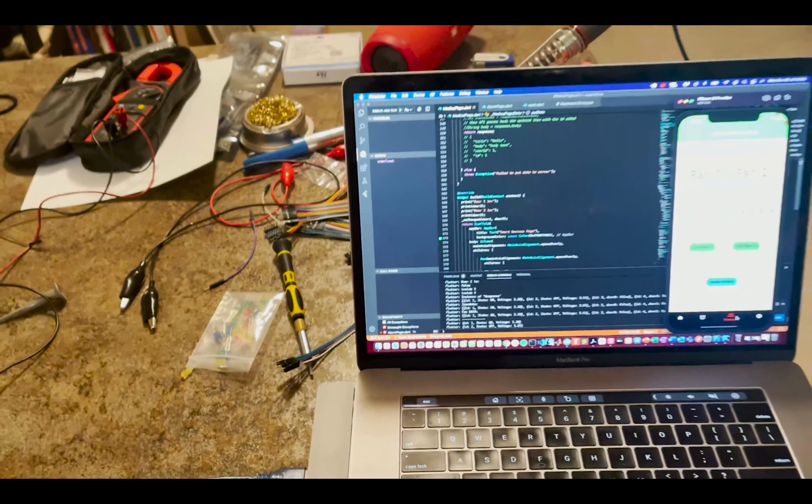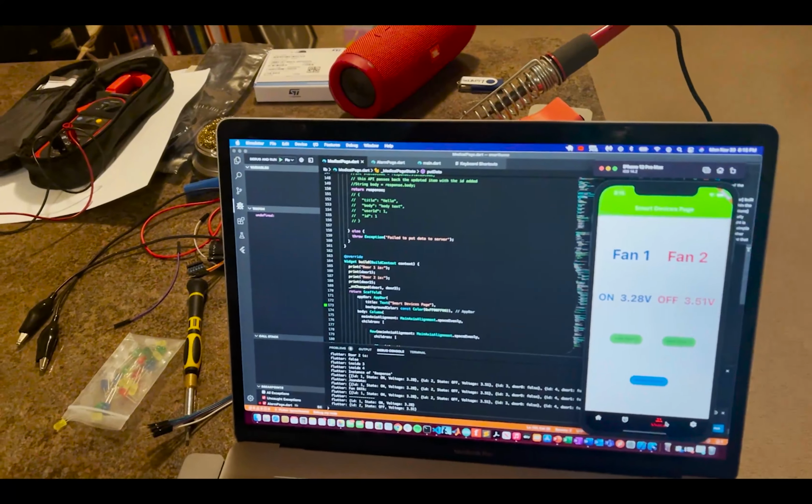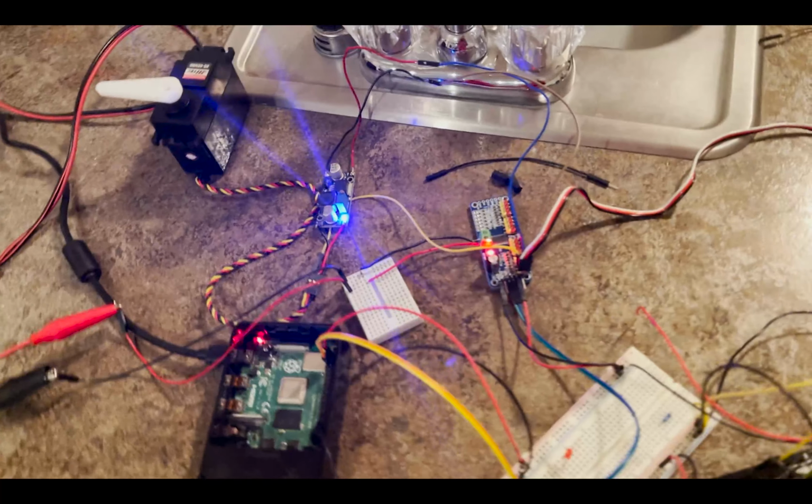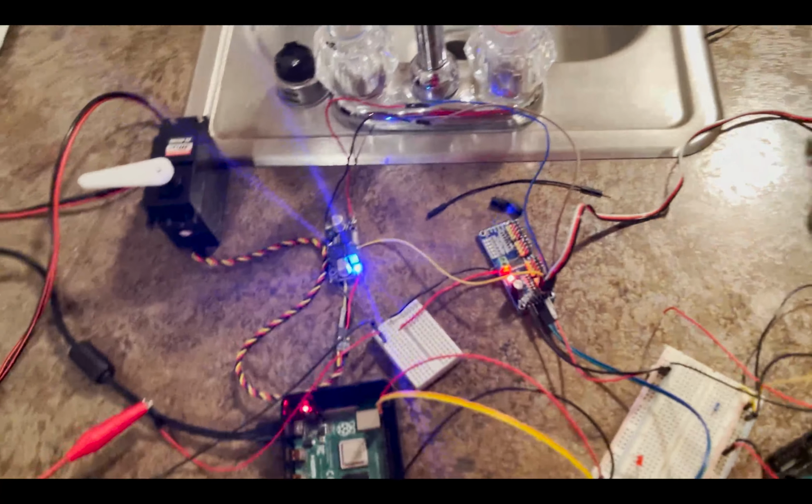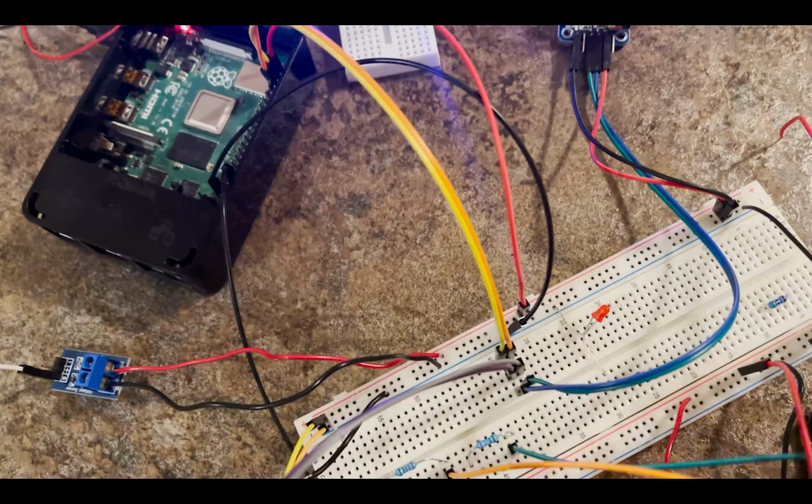Right, hey guys, this is the live demonstration of my project here. Just a quick overview of the hardware. I have a power supply, a digital servo, and an analog servo. This runs at 5 volts, this runs at 7. To solve that issue, I have a buck converter, a motor driver board, the Raspberry Pi, and the Arduino Uno, and then the motor driver and the A to D are set up over I2C.